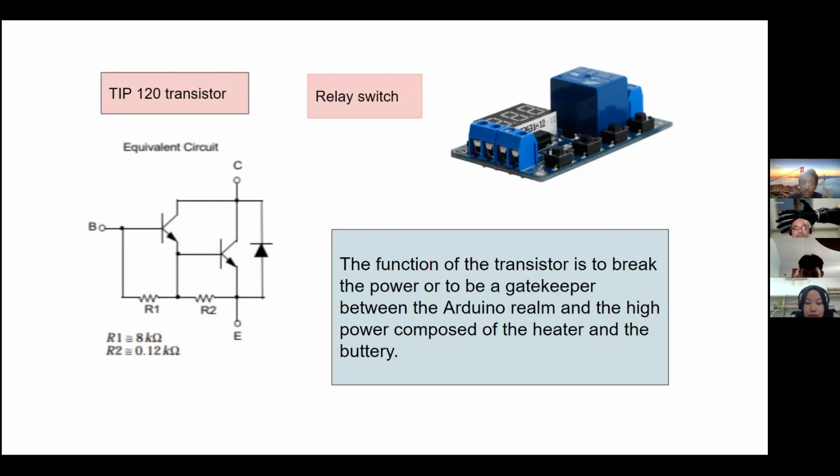Before I forget, actually, Martin, pass to another slide. We used a 1 kilo ohm resistor between the Arduino pins and the TIP120 base pin to ensure against electrical shorts. The Darlington TIP120 may handle, as I understand, 60 volts and 5 amperes, but I don't think that the Arduino will.